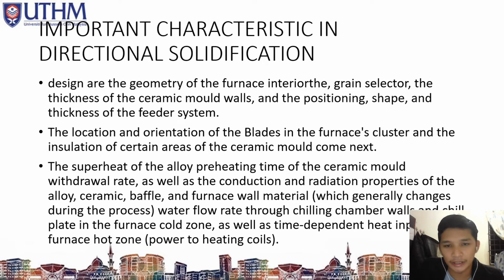Okay, first is the design geometry of the furnace interior, the grain selector, the thickness of the ceramic mold walls, and the positioning, shape, and thickness of the feeder system. Okay, next is the location and orientation of the blades in the furnace cluster, and the installation of certain areas of the ceramic mold come next.